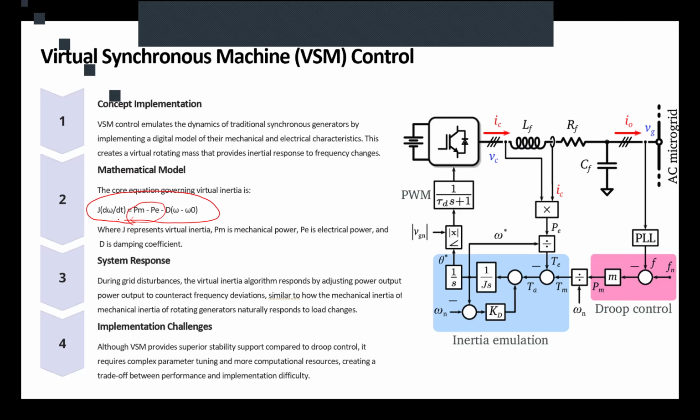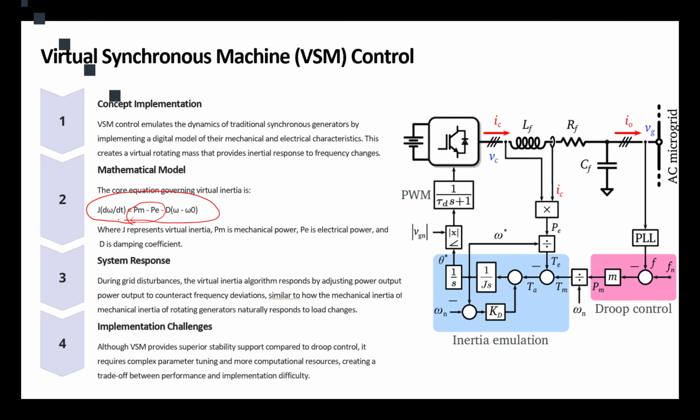So in a rotary machine, if you inject 1 kilowatt of electrical power, but your load is 1.2, you are overloading your system, correct? So the speed of the rotary machine is going to decrease. Can you visualize that? It's overloaded, so it starts to lose speed in order to provide the torque that it needs.